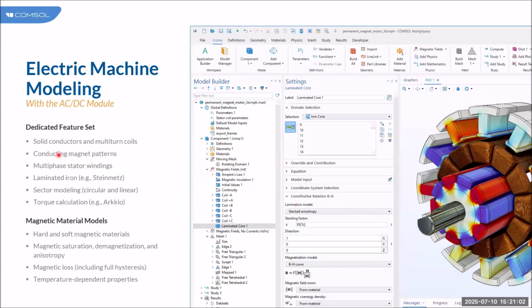As I already said, what is the number of turns of the coil, and what kind of phases you have. Here you can see the phases or the coils, which will correspond to different phases. You can either design a 3-phase motor or an N-phase motor, like a 5-phase motor. But all are possible by defining clearly what is the excitation given to this motor, as well as the number of poles, the number of slots and all. So once it is given, we will be ready to simulate it using FEM. And the next step will be meshing the whole geometry for FEM, and then we will conduct a particular study. So the whole process of electric machine modeling is done in COMSOL in this approach.